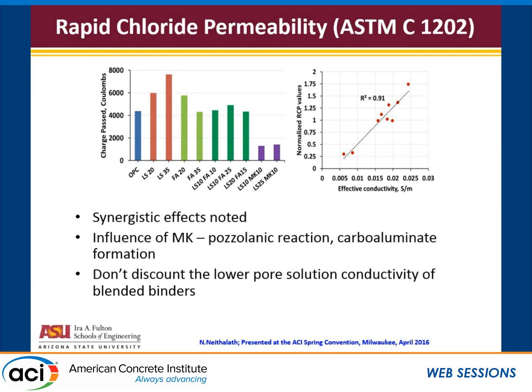But if you bring in ternary mixes with fly ash, ternary mixes with metakaolin, you suddenly have, so 25% limestone, 10% metakaolin, look at where it's about half of the chloride permeability. This value is pretty much what you get when you have silica fume, close to that. So again, you're using 25% of limestone in this mix. Same reason which I told earlier, the sulfate AFm being replaced by carbonate AFm and a lot of pozzolanic reaction products being formed.